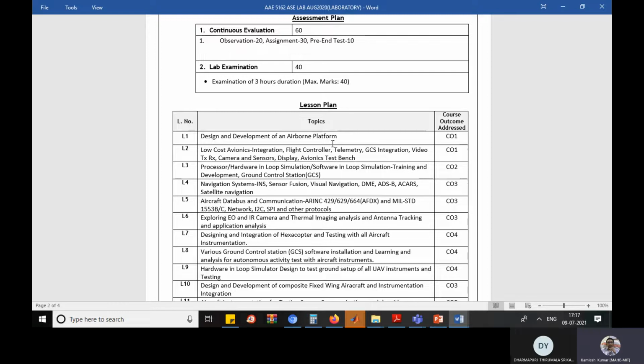Okay, and the next part, people are using foam materials, correct? You have different types, either XPS foam, the normal foam materials you have seen, or maybe PU foams. So with these different materials, they cut the particular shape as per the 3D design and then put some material over that. It can be a glass fiber coat or something like that, or you insert some hard material, either carbon tubes or maybe some skeleton. Okay, so this is another type of design.